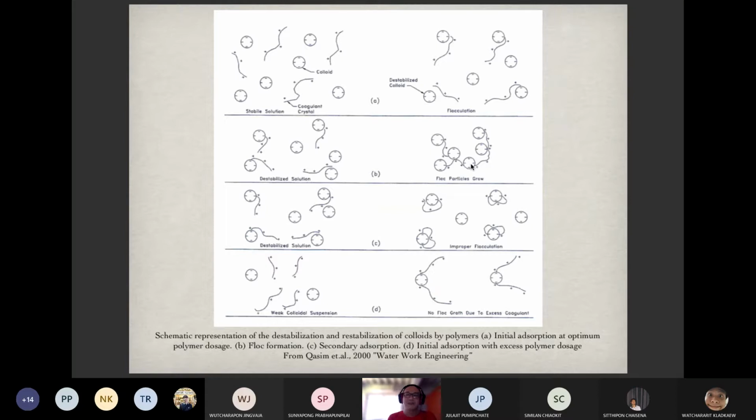If you look back at the previous slide, you will always see the sedimentation process is located after the coagulation and flocculation process, because this sedimentation tank we normally use to allow the floc, as we normally call it, to settle to the bottom, and only the clear water, the clear supernatant, can be discharged or sent to the next unit operations.